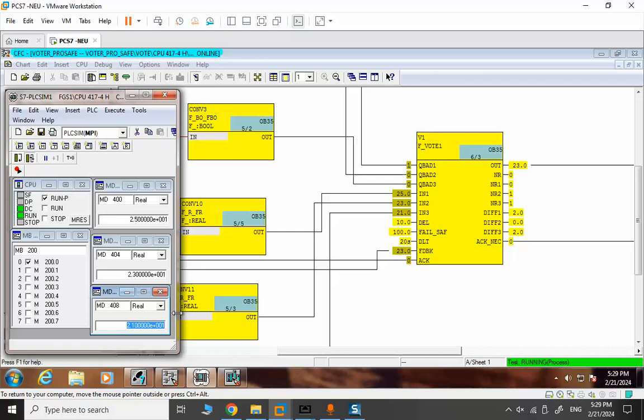So consider that one of these signals is changing dramatically, as we have bad luck. 2 and 3, like 10. It's a huge difference. We can tolerate this problem for 20 seconds for this delay time. We have one bad quality signal. The other signal has a huge deviation, and after the delay time, if we cannot solve this problem, we have the shutdown here, and the failsafe will be in output after the delay time. So let me return everything to normal values, 22, remove the bad quality, and press acknowledge.